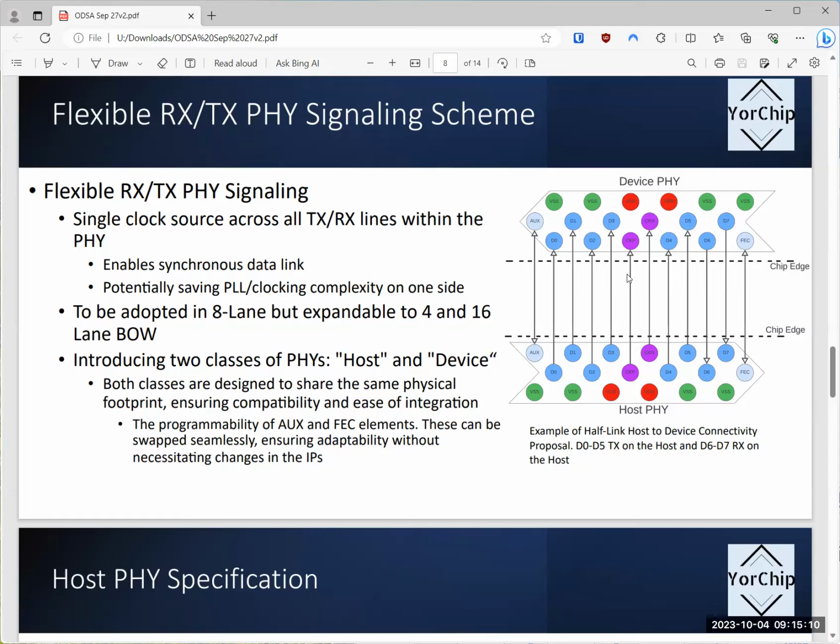Well, an example scenario is that you have one chip that has a lot of chiplet interfaces around it. It's an additional use case, right? If we do it in this mode, it enables us to use, say, this 8-lane with every single IoT chip, which gives flexibility. If it wants to connect to a more traditional one, which is actually something we are doing, it just takes advantage of 2 lanes, one in RX and one in TX.